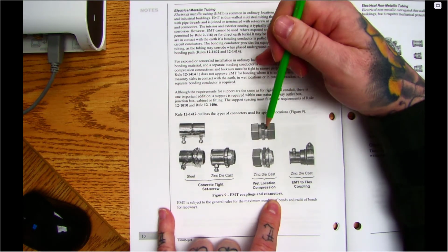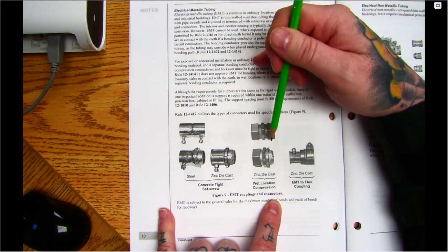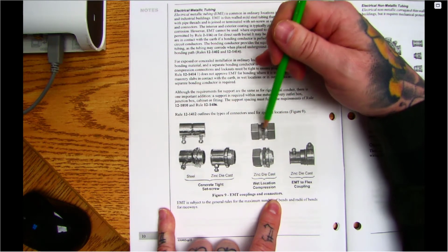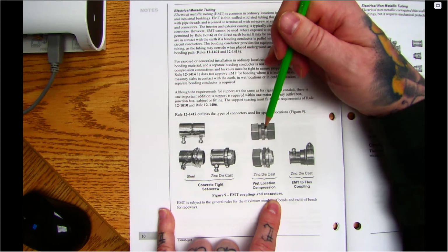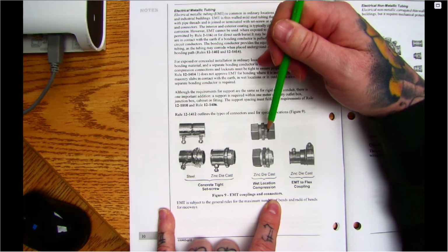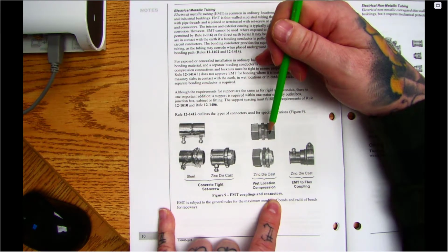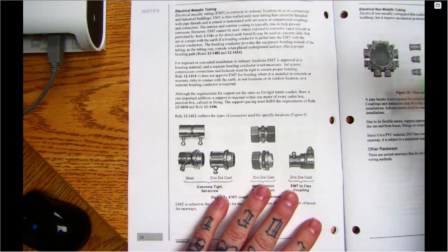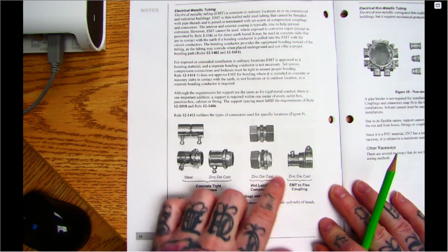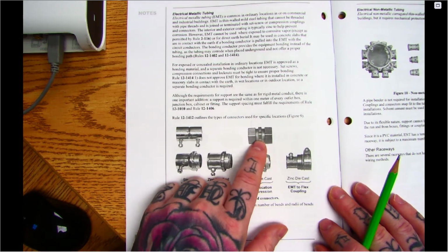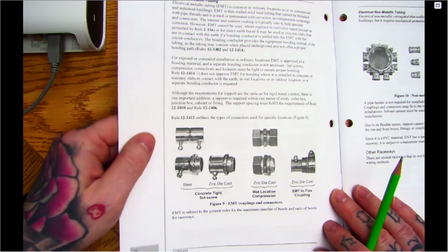And I've had to do that in the field. And my thought behind that is these are compression fittings. They don't have set screws. These break really easily, and if they break, come apart, then you've lost your path of continuity as well too. So that's why it's made sense that when I've always had to pull a bond in there, is because these fittings are not. All it takes is one loose fitting, and you've lost your bond, right?